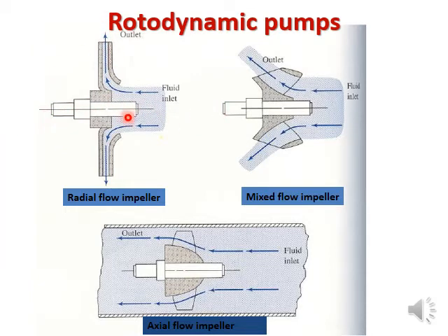So the axis of rotation is here, the plane perpendicular to it is here. So once it enters here, you can see, it moves through the impeller but remains in this plane. If you consider flow relative to the impeller, flow is radial. Otherwise, it is spiral.